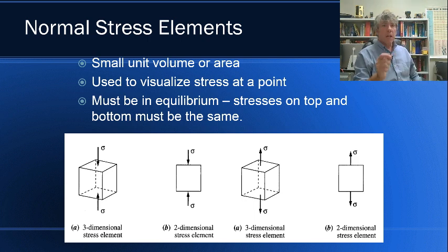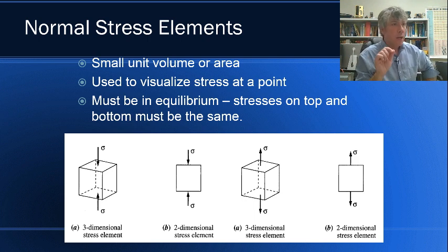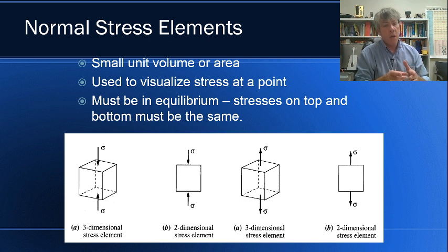All right, so when we talk about stress elements, we're talking about something that has zero size, something that exists at a point. And this is really important because if you think about the round cross-section where you have direct normal stress, you could keep zooming in farther and farther. We don't have to talk about just, say, 1 square inch of area and how much force that square inch is applying to hold the material together.